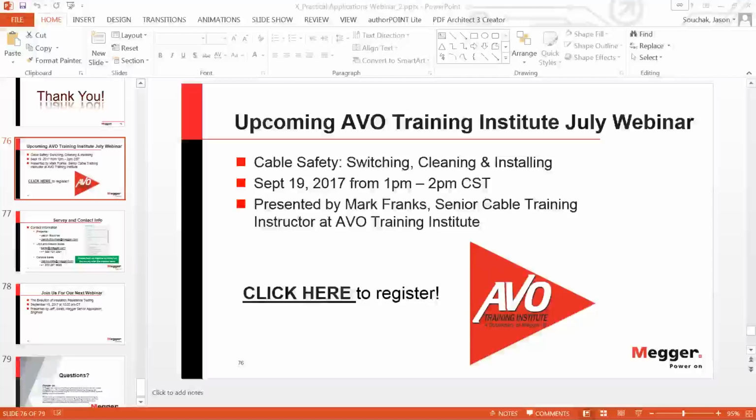Unless you have access to a manhole system where you can actually put PD detectors in each manhole, so you have a fairly short distance, maybe 400 or 500 feet between manholes, then it's fine. Now, if you don't have access because you don't have a manhole system, then on online PD testing you have very much the same or worse condition, like I said, because the voltage level is limited. So attenuation is an issue whenever I have a pulse traveling on a piece of cable. It's not just limited to offline PD testing.